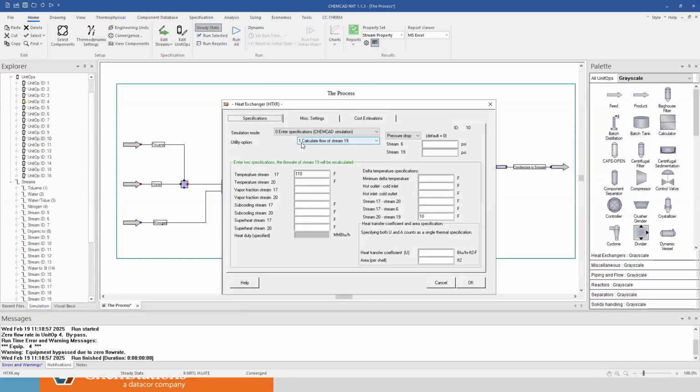See, I was underestimating the amount of water needed for this process. And this is just using the simple unit operation. We haven't even gone into the rigorous calculation. There is something else in here. I didn't take into consideration the pressure. And when we are doing a heat exchanger, we need to switch. So I can actually add a little bit more in here.